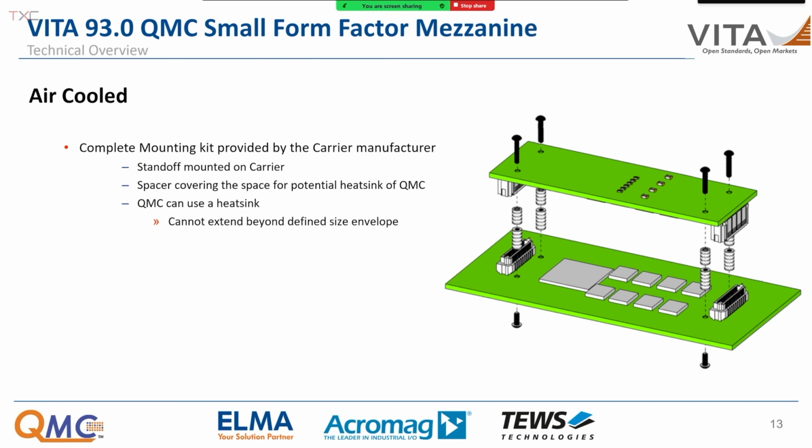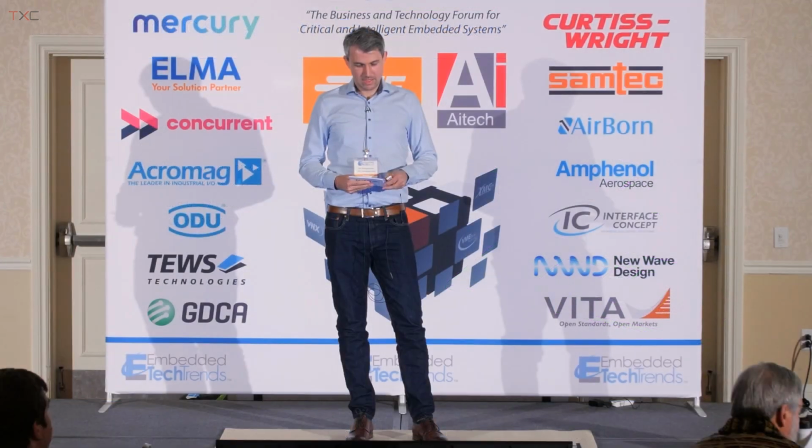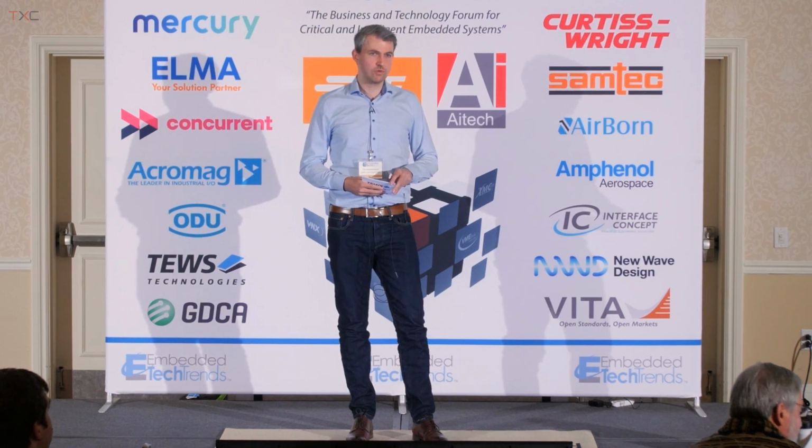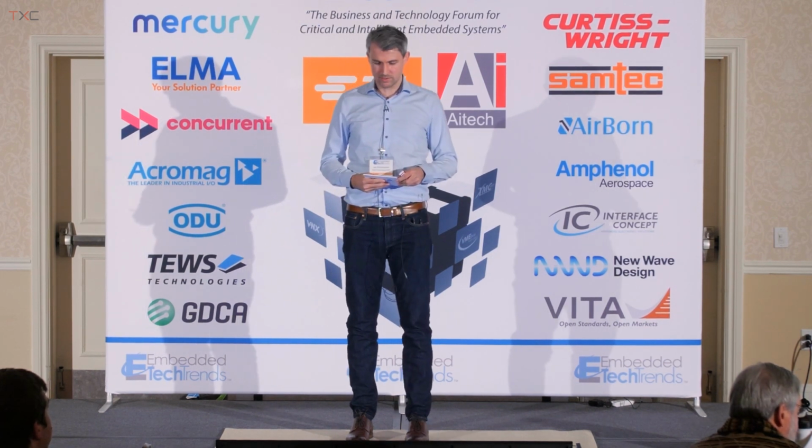So regarding the cooling concept, we'll handle air-cooled and conduction-cooled real quick. What you can see here is an air-cooled QMC on an air-cooled carrier. And the mechanical fixation concept of a QMC follows a very simple rule, and that is that the carrier provides all mounting hardware. On the one hand, that means that the complete mounting kit has to be provided by the carrier. This includes the screws and spacers, and on the other hand, that frees up the QMC designer from worrying too much about mechanical stuff, and also the integrator from compatibility issues.